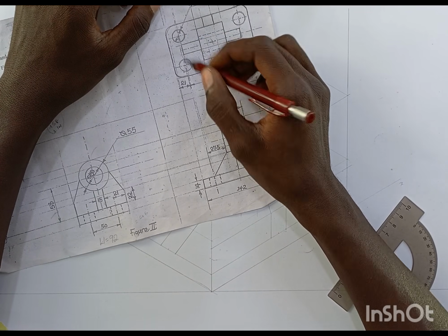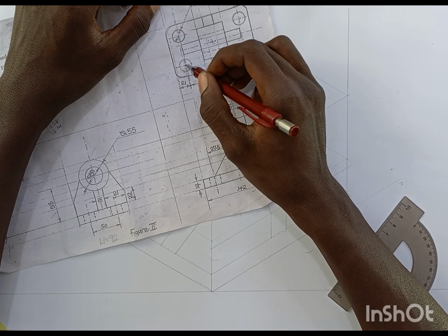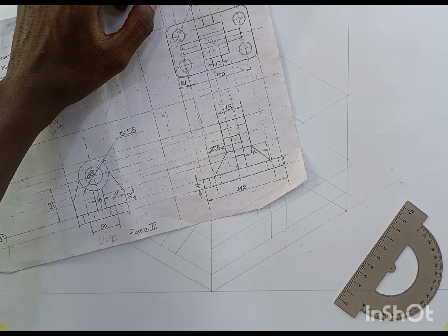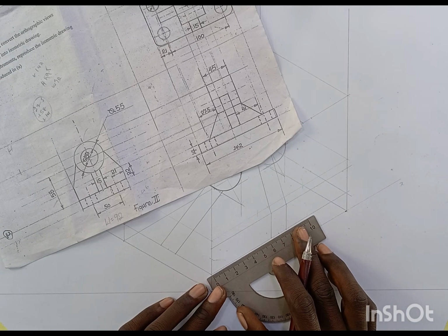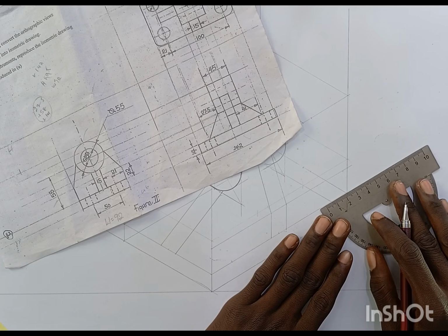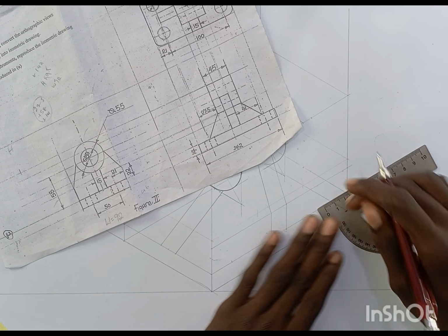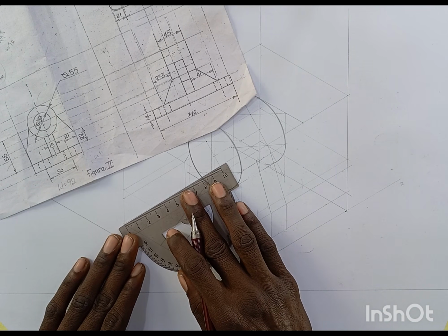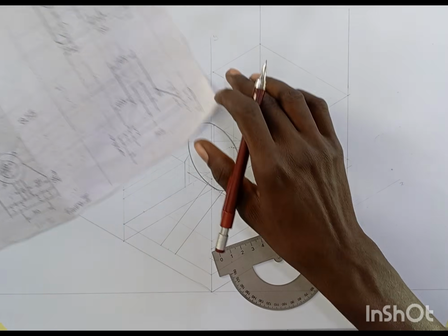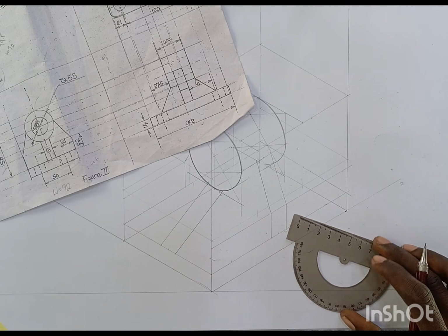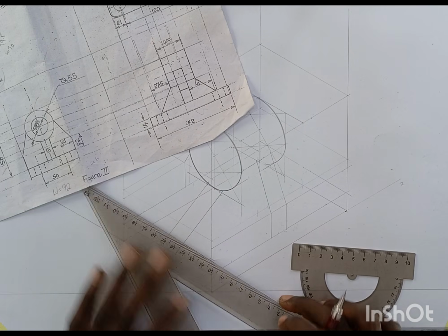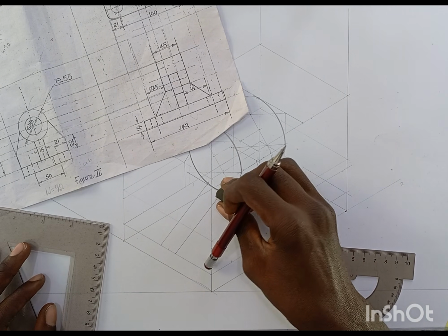So now here we are going to first take the center line of this circle, which from here to here is 21. It's giving us 21. So I'll measure 21 from this side. Also, same thing I will do here. 21 from this side. And then I'll measure 21 from this side also. Then from the other side, this cylinder is going to cover it, so we don't need to give any measurement there. So now I will connect these 2 points to have the center line where this slanted line will touch. So now let me remove it.